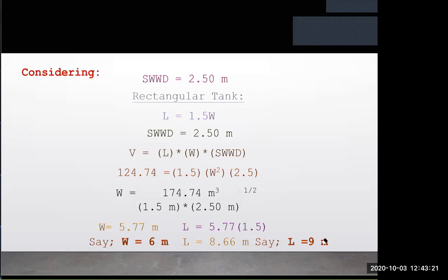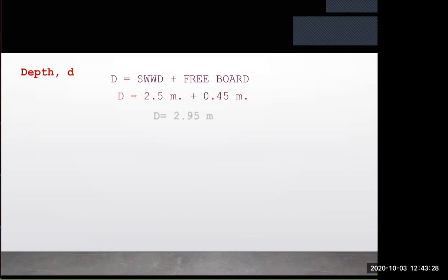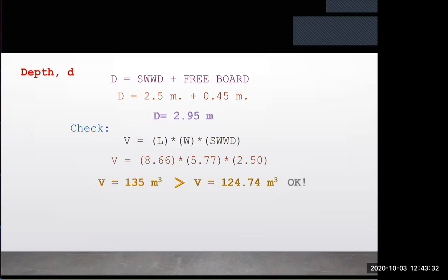Now, when you are designing, it's not good that you only have one design. Iisa lang, you do not have an alternative. So, you can also have another depth here. So, let's say that the total depth plus the freeboard, that is 0.45. Remember a while ago, I told you that the depth is equal to the maximum depth that the wastewater could now occupy.